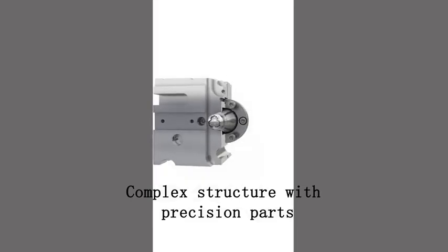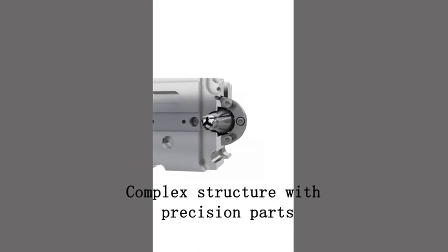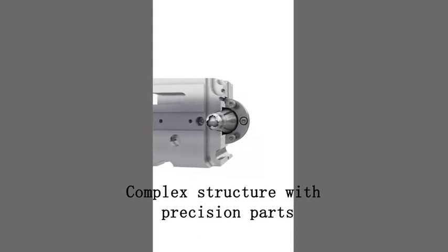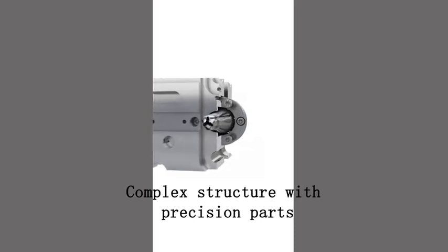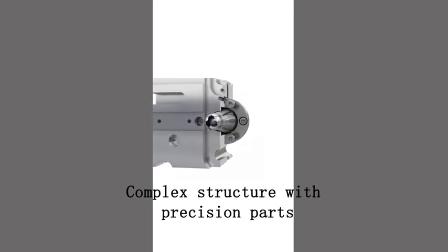Collapsible cores involve intricate structures made from highly precise metal components, contributing significantly to additional mold expenses. As a result, they are most effectively utilized in scenarios of high-volume production, or in instances where alternative mold designs struggle to accommodate the demands of injection molding for a particular part.